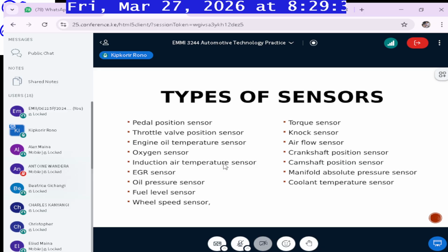It also shows you the oil temperature. The oil temperature can rise, by the way, for a number of reasons. For example, if you've used the oil for a very long time and you have not changed it, the oil breaks down after a very long use. It breaks down the specific chemical structure of that oil. After very repeated use, under very high pressure and very high temperature, it breaks down. And it reaches a point where it loses the ability to carry away the heat or function even as a lubricant.